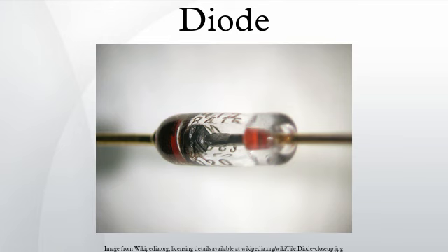When a P-N junction is first created, conduction band electrons from the N-doped region diffuse into the P-doped region, where there is a large population of holes with which the electrons recombine. When a mobile electron recombines with a hole, both hole and electron vanish, leaving behind an immobile positively charged donor on the N side and negatively charged acceptor on the P side. The region around the P-N junction becomes depleted of charge carriers and thus behaves as an insulator.